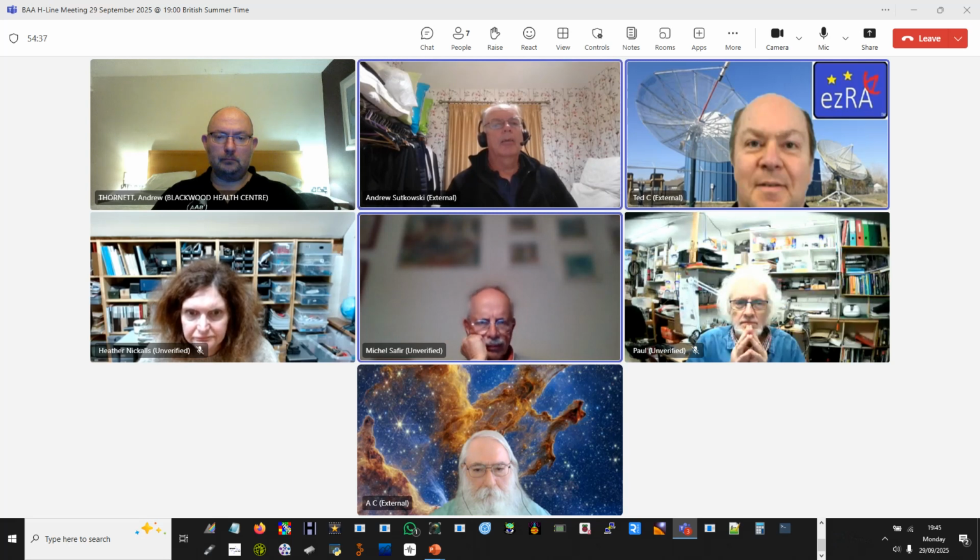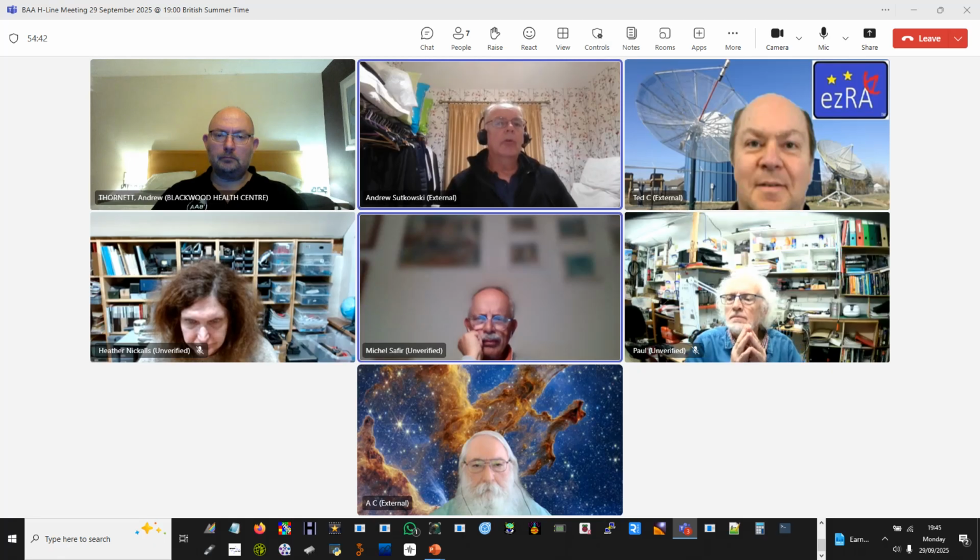I have used both SDR Duo and SDR Play, with GNU Radio and the West Virginia University Radio Astronomy Laboratory programs, and they record spectrums every 10, 30 seconds, whatever time interval you put. And I used the Duo with interferometry using two 750mm feed horns, but on the sun, so lots of signal there. But when I get a chance, I will look at it with EZRA.